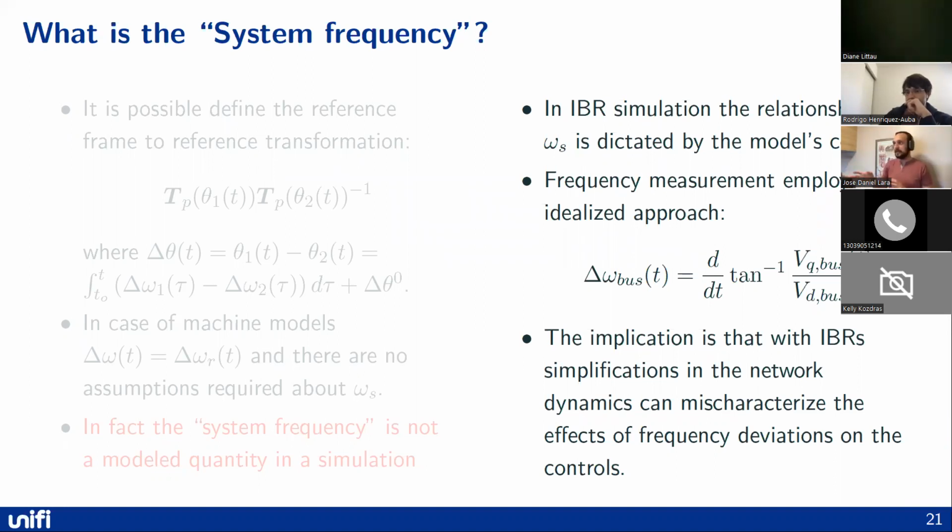That allows it to demodulate any three-phase signal that exists in the system. But in the case of an IBR, the relationship of the IBR with respect to the system frequency is governed not by rotating-mass equations of physics, but is dominated by how the controls are configured, right? And there are many proposals of different configurations. There are people who want to get rid of the PLL, we should have it or not have it, and there's the droop or not the droop, or virtual synchronous machine, etc.